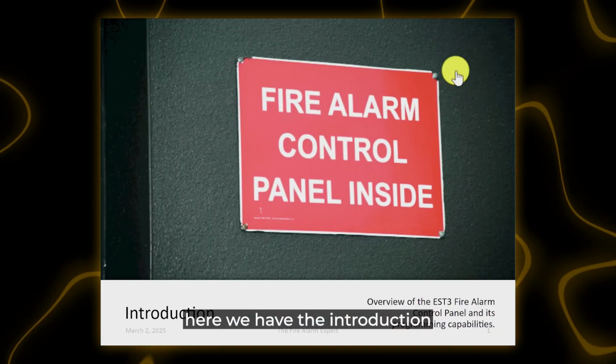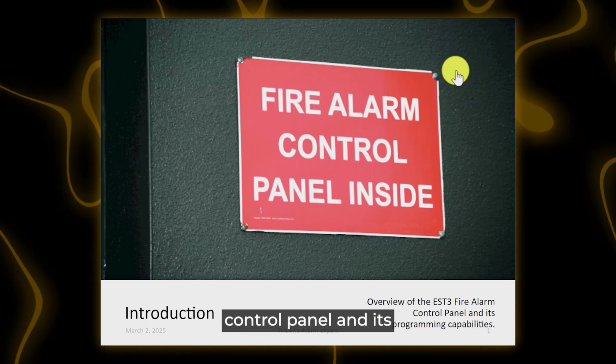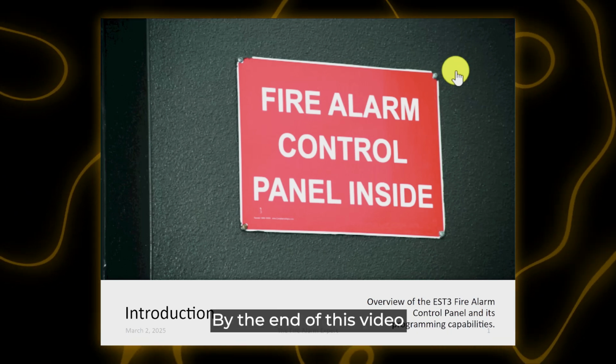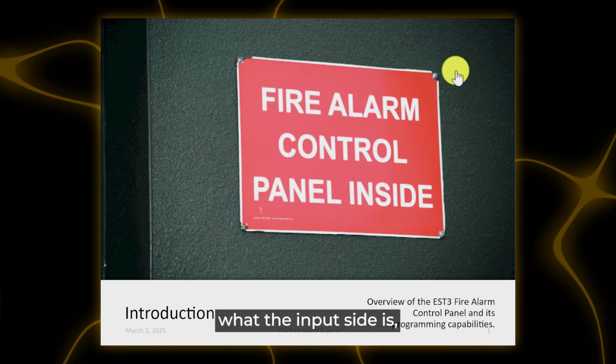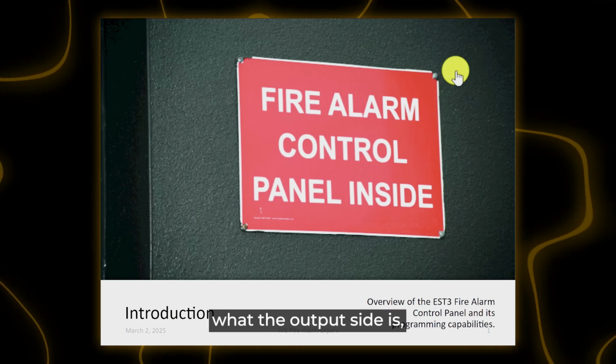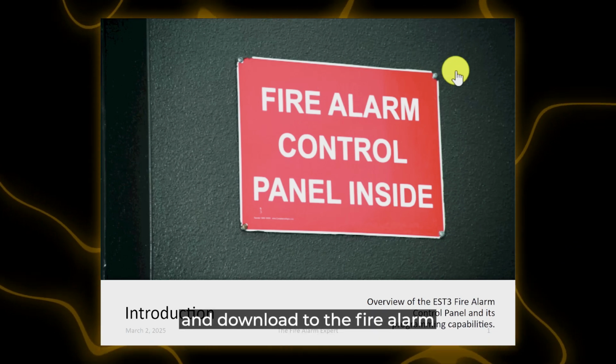Thank you for joining me. Here we have the introduction of the EST3 fire alarm control panel and its programming capabilities. By the end of this video, you will learn what a rule is, how to write a rule, what the input side is, what the output side is, what the syntax is, and how to actually compile and download to the fire alarm control panel.